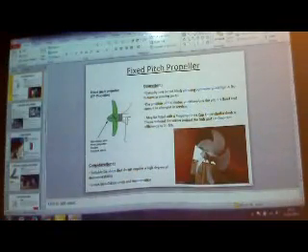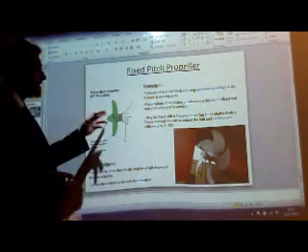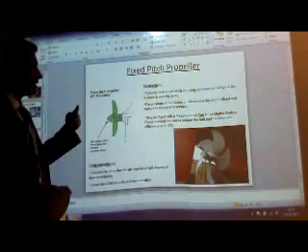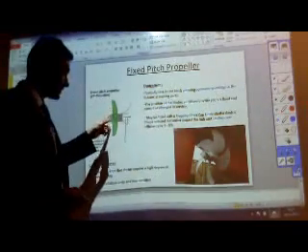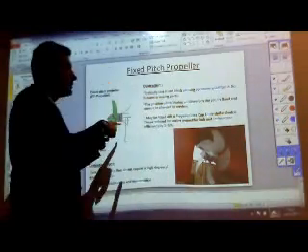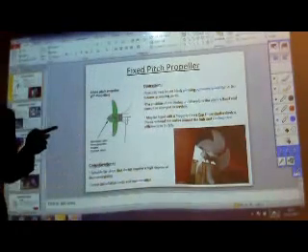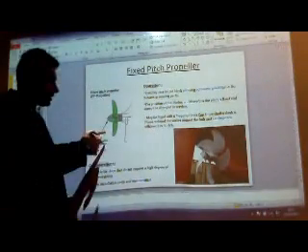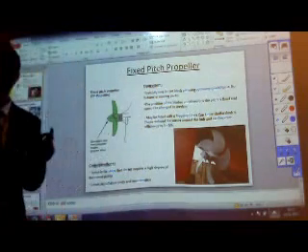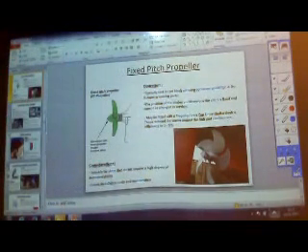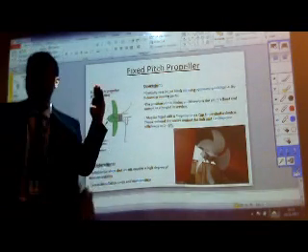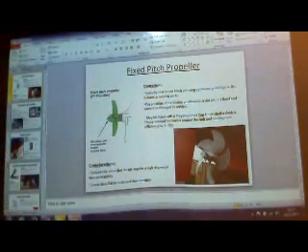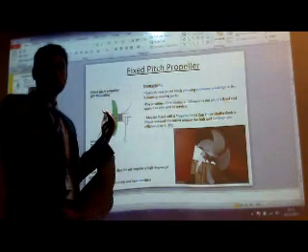Yeah. What is pitch basically? Well, pitch is basically the distance that the propeller, from its center point, will travel when it completes one full revolution. When a propeller completes one circular revolution in water, we are going to measure the distance that it is going to cover. That would be the pitch of this propeller. It is related to the angle at which the blades are designed. Yeah. That is what a fixed pitch propeller is. Its pitch is going to remain fixed.